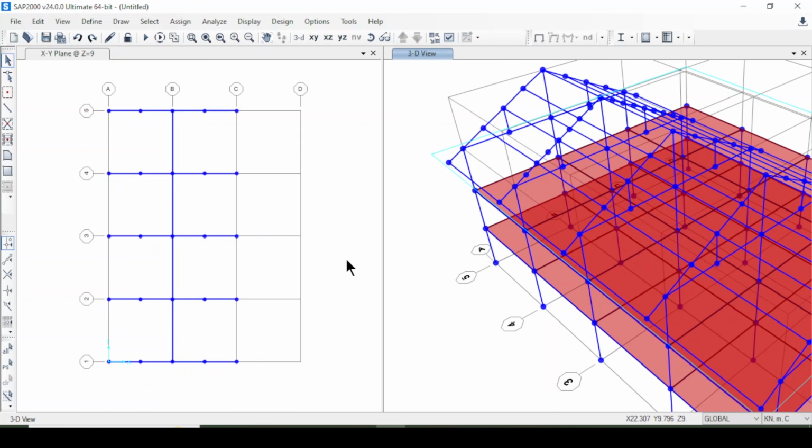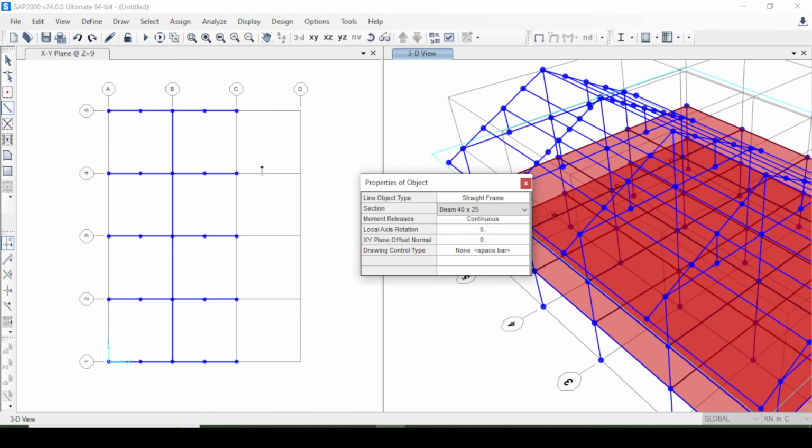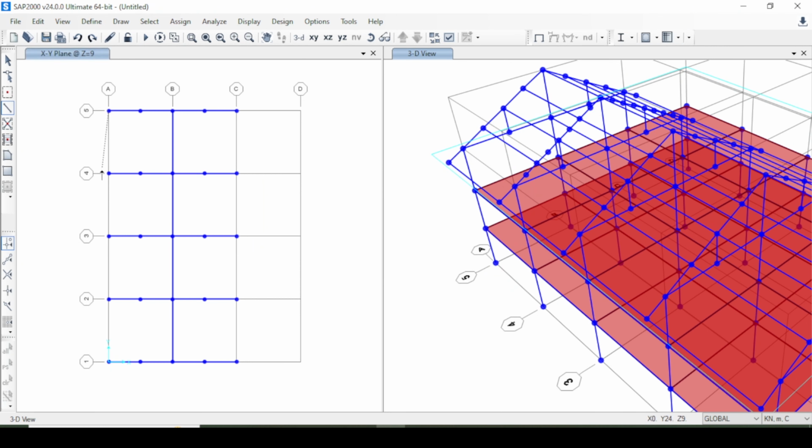Like here a few beams are required in these portions, and we will create slabs as well. So I'm coming here to the beams. Like we have beams here, I will close this one, and I will create beams here. Look here in this portion, and here as well, and here. So we have drawn beams in this portion. This is external, it is inclined, so we do not have beams here, but here are the beams. Here is a beam, and we do not have beams here. So this is purlin and beam purlin. That's why I have to create a beam here.